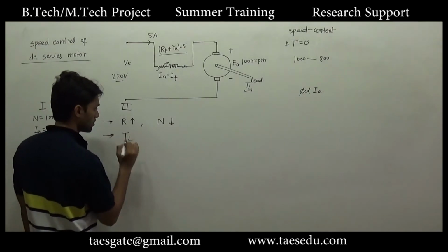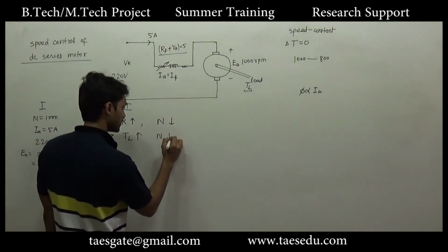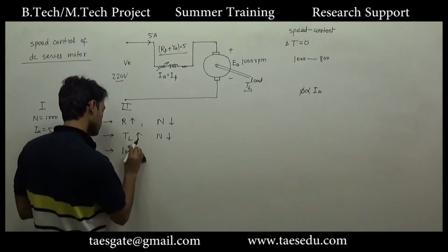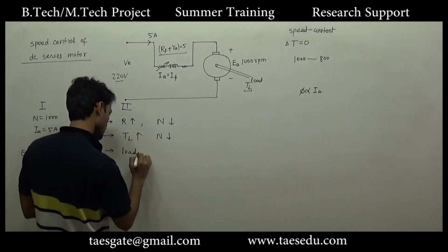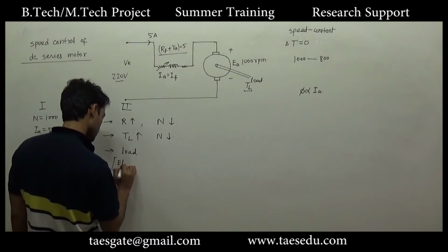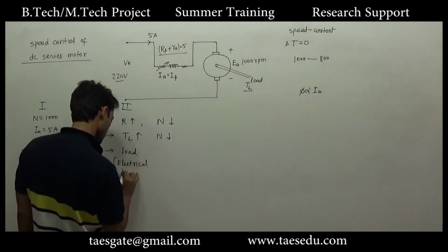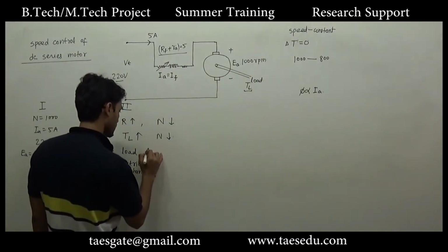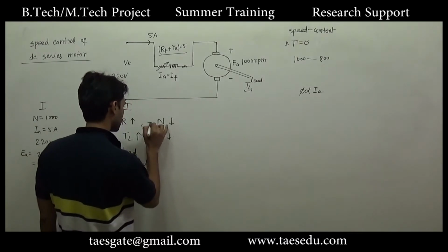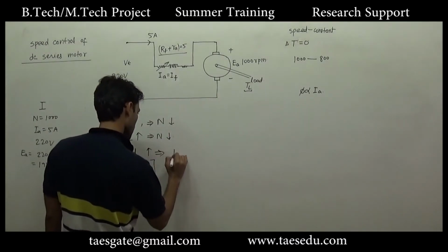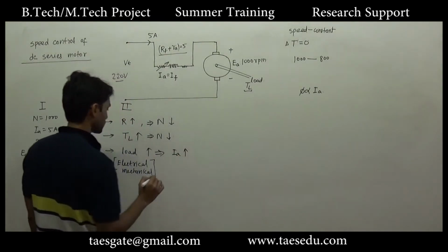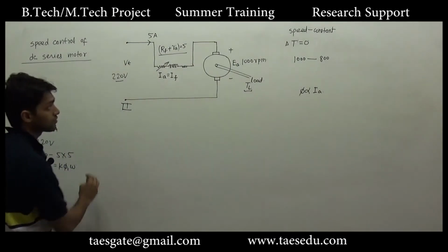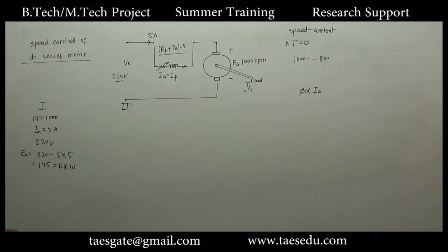If you will increase load torque, speed will decrease. If you will increase the load, whether it is electrical load or it is mechanical load, electrical or mechanical, if you are increasing the load, armature current will increase. Now in the same question we will again make some changes.